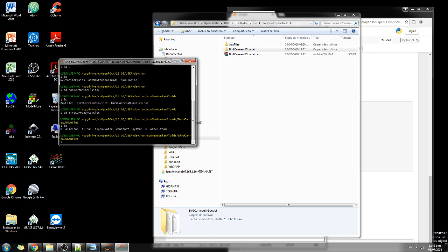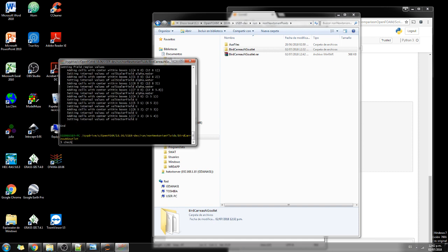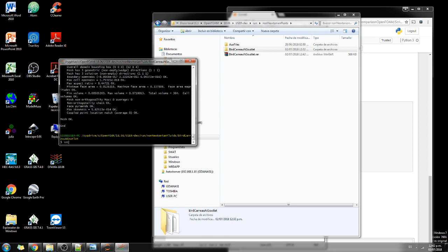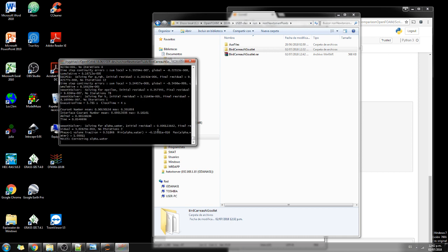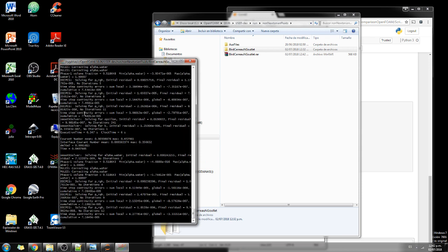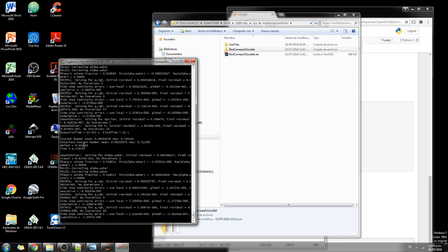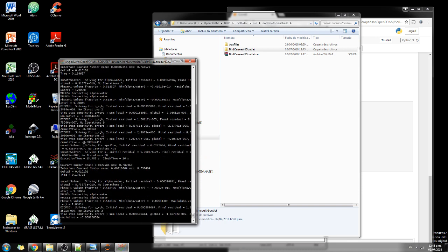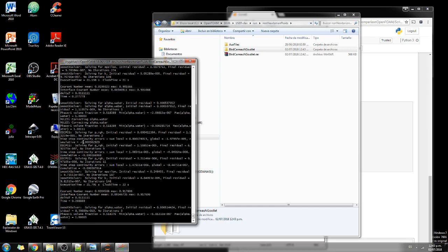Then here we just have to follow some commands: blockMesh, then setFields, then checkMesh, and then interFoam, because we are going to deal with interFoam, and it will run for 6 seconds where the delta t is 0.06, so it will take some time. Okay, let me show you. Look.